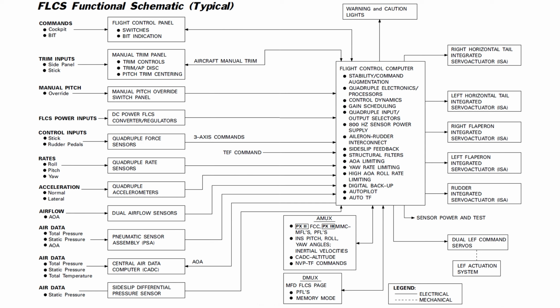At low angle of attack, the pitch axis of the FLCS operates as a G command system. As AOA increases, FLCS switches to a blended G and AOA system, providing warning of high AOA and low airspeed states. Roll rate is limited, and maximum roll rate decreases as a function of low airspeed, high AOA, and horizontal tail position.